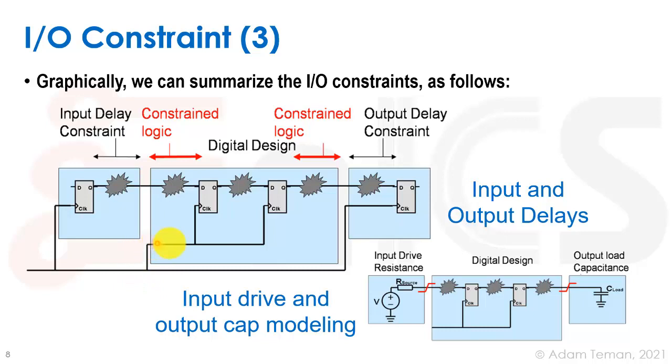Think that if we have a clock propagation delay that's a whole clock period, then we're never going to be able to meet timing on such a path. And the same being said, if we have a propagation delay of a whole clock period over here, then we're going to have such great useful skew that we don't care what we do here in terms of optimization. We're always going to meet timing. So really, these are the things that we have to take into consideration, and I would rather put a max delay on the input and a max delay on the output, and that's how we would meet the timing.